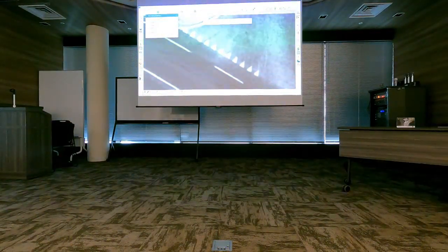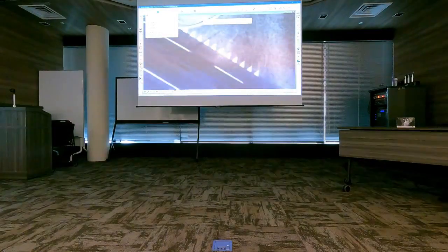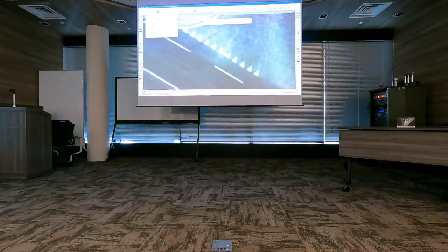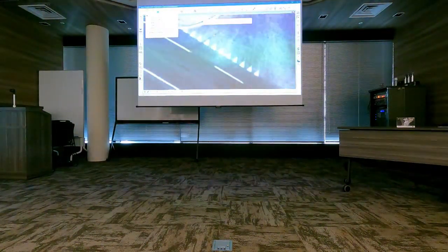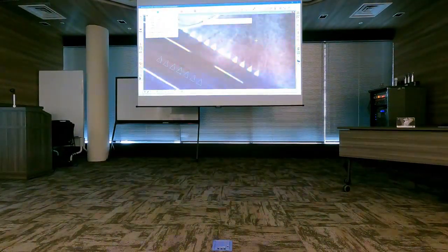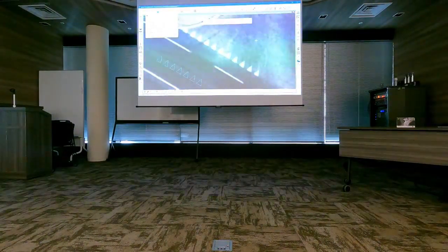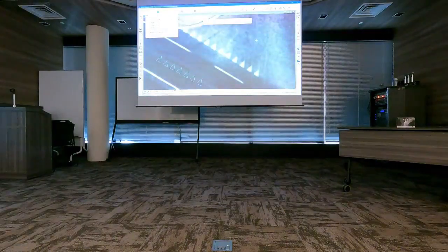I need to know the size of the triangles, and I need to know the approximate spacing. And I do 2 mouse clicks, click, and click. And there's no fitting in XY to the point cloud, so I can place it anywhere. It doesn't look at the intensity to get the XY position. This one only uses the point cloud to get elevation.